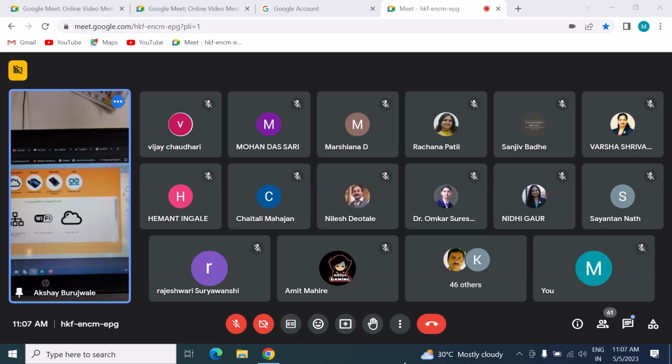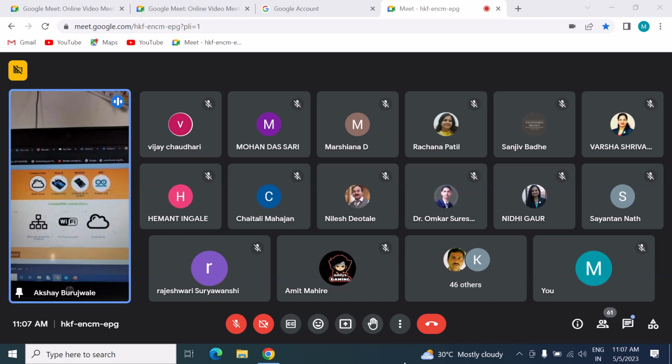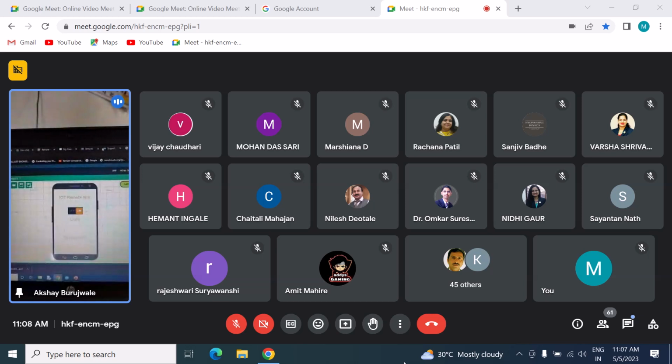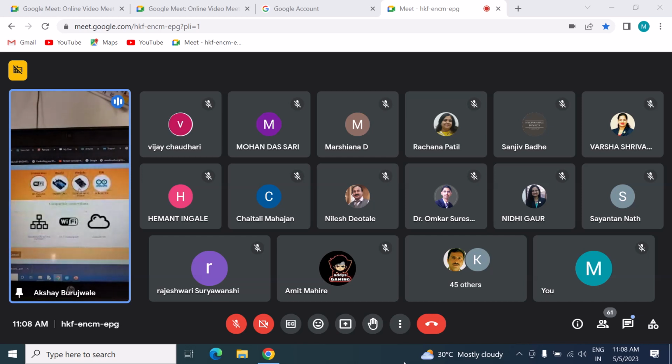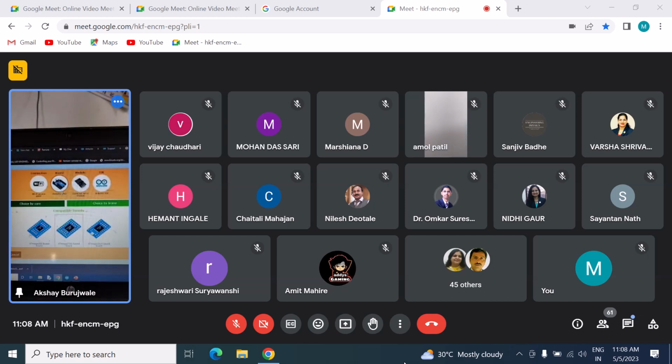Okay, RemoteXY provides us the opportunity to construct a mobile app for remote controlling, and a number of things you can do with the remote application. So we are connecting with the Wi-Fi access. So Wi-Fi access is selected and applied. Okay, there is another setting, and the second is your Arduino board. So we have selected the ATmega328 board.